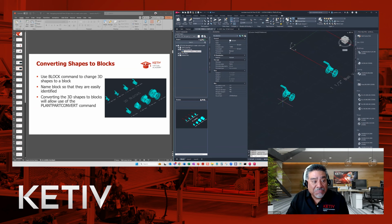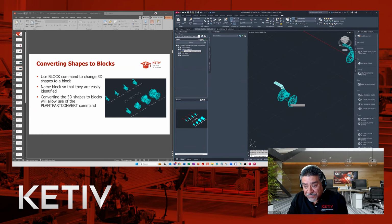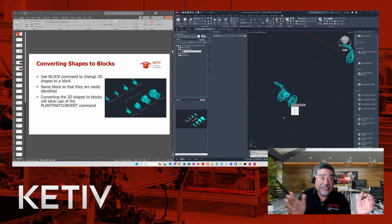So now that this is a block, I can use this command over here, plant part convert, and that's going to go through the process that it needs to be able to see this in the catalog. So over here, if I go plant part convert, I can select this, and it's going to go through a couple of steps to where I can add information to this in order for it to have connection points within the valve that it's going to connect to, like a pipe or something else within the model.